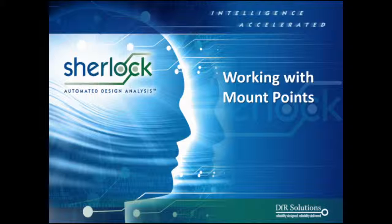And so why would I, as a user of Sherlock, care about mount points? Well, the mount points provide the boundary conditions for the finite element analysis. So if you're doing a vibration simulation or a shock simulation, that's how the board is constrained, and that's how the boundary conditions are defined. So wrong mount point, wrong vibration results. Correct.